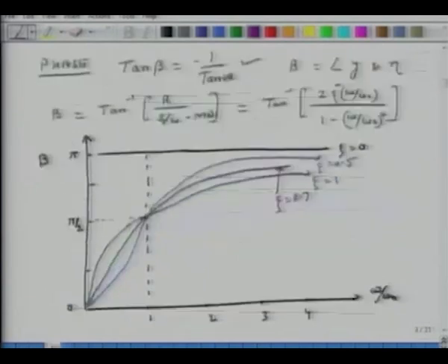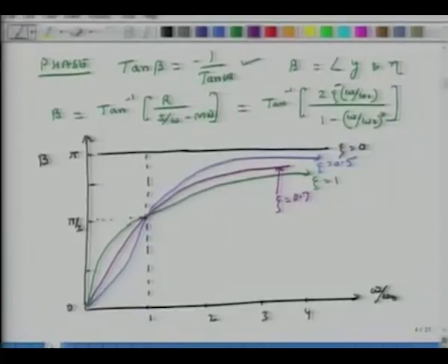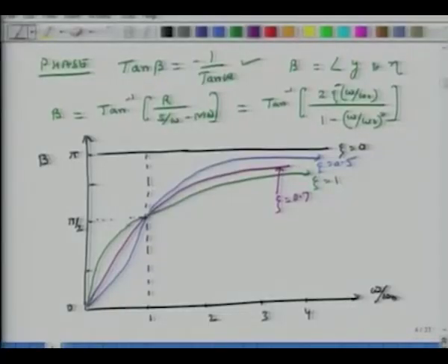What this curve shows is that, let's say if I pick eta anywhere between 0.5 and 0.7, I have a fixed phase difference which is a little less than pi, and if I keep my omega divided by omega naught above a ratio of 2, then that fixed constant is the same for all frequencies. Based on this, I know how to calculate the phase difference between source excitation and whatever the instrument is measuring, and also I know how to translate that voltage into the actual displacement.